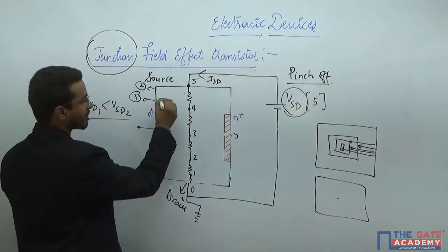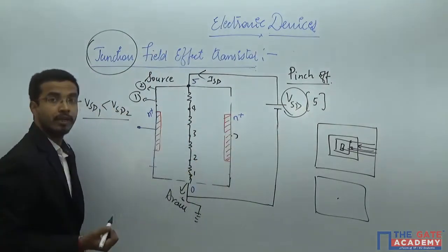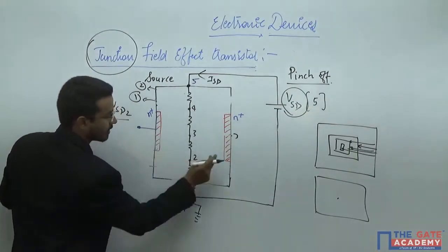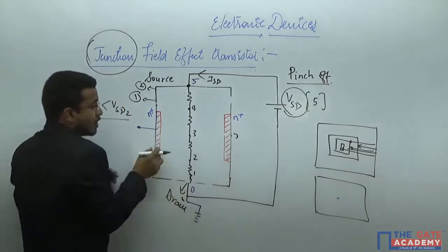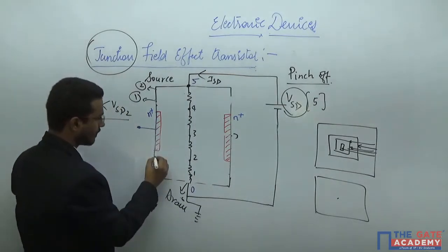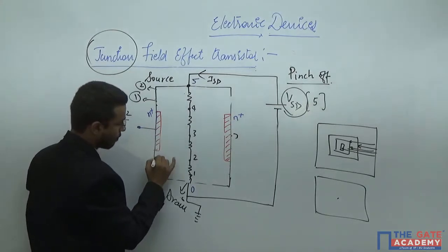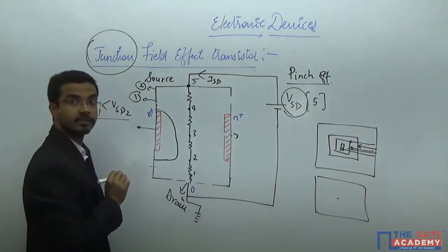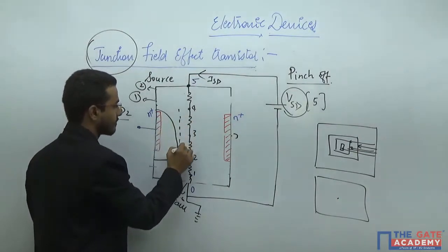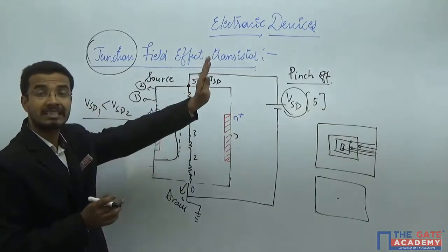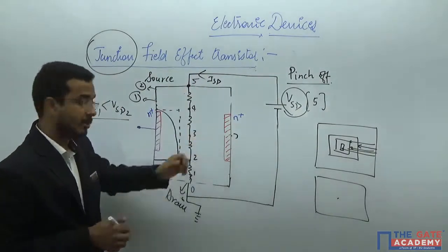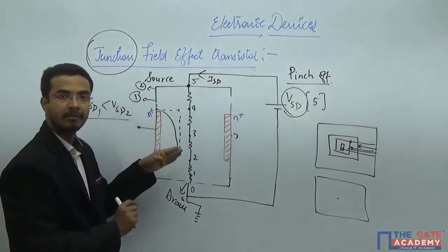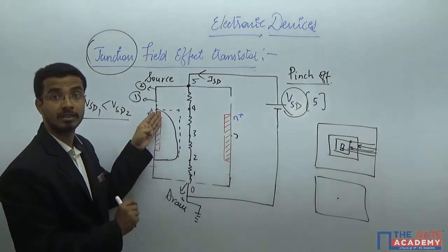Now, instead of the sharp such type of shapes, you will get modulation in the shape of the depletion width. That means here at this bottom surface toward the drain side, you are having more reverse bias. So you will take from here that the bottom side is having more reverse bias and the upper surface is having less reverse bias, like this. So instead of these dotted ones, whatever you have assumed previously that throughout the device the voltage is same, then you will get these dotted ones. But at this time you will get the wedge shaped. That means this depletion width is not throughout constant.